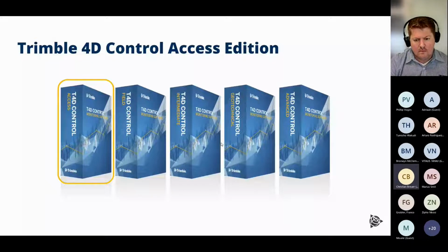T4D intermediate, as it says, as an intermediate version, it can do all the data processing and can show you some basic analysis. T4D geotechnical is a pure version for those of you who have a site which doesn't require geodetic monitoring. So it can just take the data of geotechnical sensors like tilt sensors, piezometers, crack meters, and so on. And advanced, as you can imagine, is a thing that can do everything, from geotechnical monitoring to total station monitoring with a full-blown set of analysis tools.